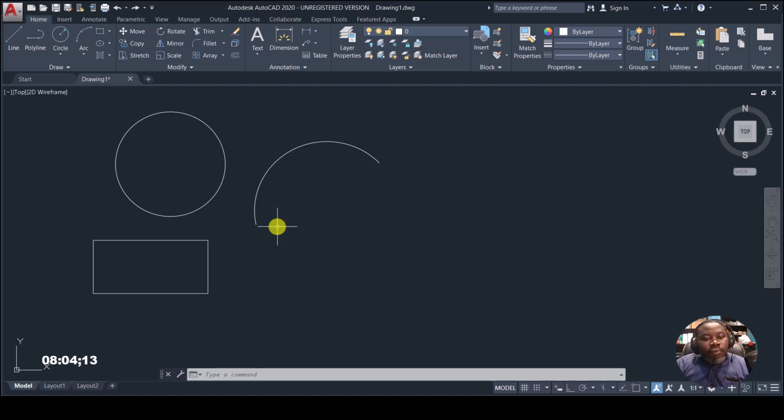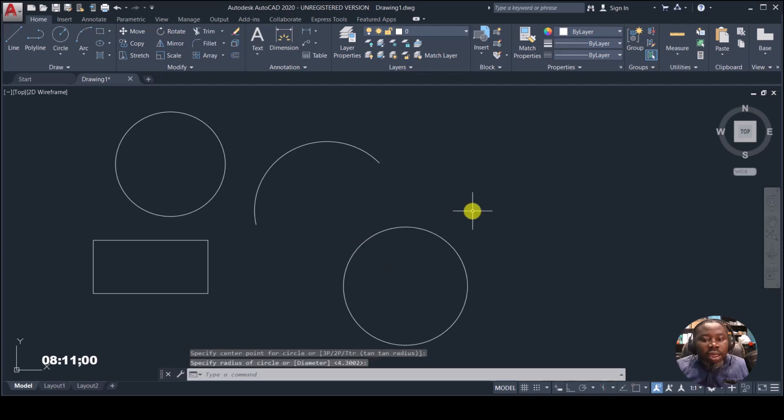All right. So now the next tool that we'll be looking at is also importantly a very useful tool. It's called erase. So now you want to erase an object. Don't forget the term object refers to whatsoever you draw, whether you have drawn a line, an arc, a circle, or a rectangle. General name is object. So now you want to delete or erase an object. Very easy to use. This is the erase tool.